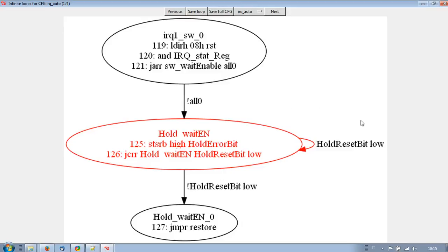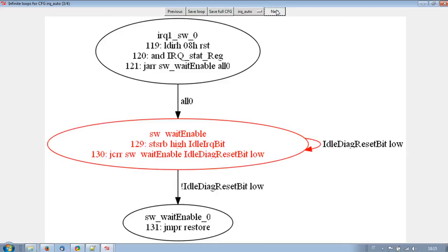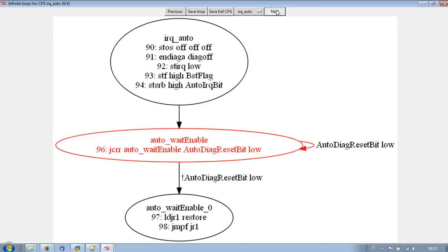They keep the load driver in a blocked state, waiting for the main microcontroller to reset a flag as a signal that the load driver can continue its operation. This occurs in all four cases, and this is the expected behavior since this is error handling.